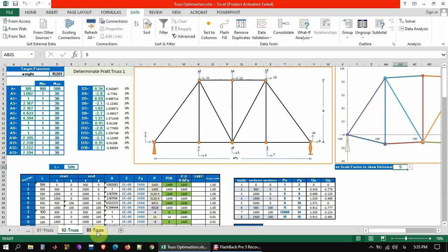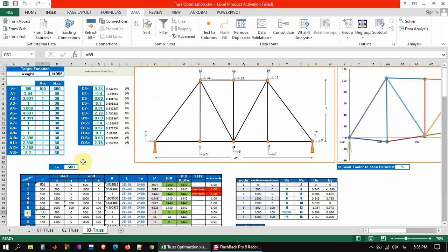So let's see the third example of truss, and as you see, it is the same as the last structures, but degree of freedom number 9 is restrained, and the structure is the same, but just the reactions of the structure are increased to 4 degrees, and actually we have these degrees of freedom in here.